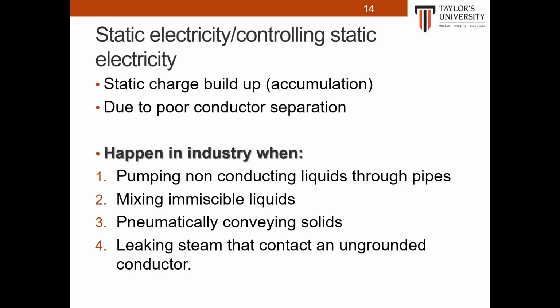The best design methods for preventing this type of ignition source are developed by understanding the fundamentals of static charge, and by using these fundamentals to design specific features within a plant to prevent the accumulation of static charge, or to recognize situations where the buildup of static electricity is inevitable and unavoidable. For unavoidable static buildup, features are also added to continuously and reliably inert the atmosphere around the regions where static sparks are likely.